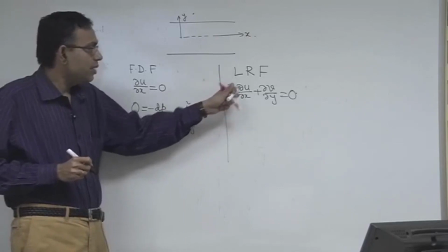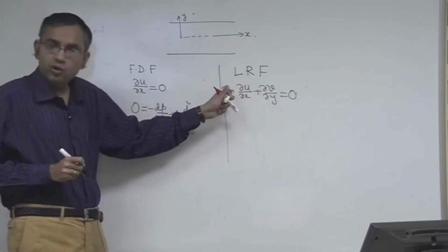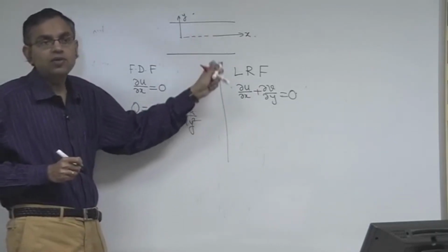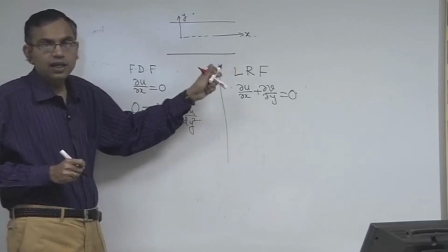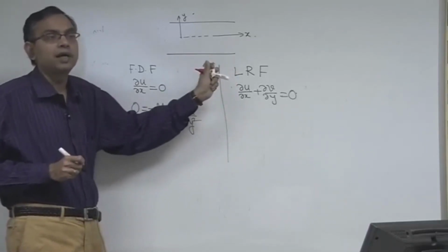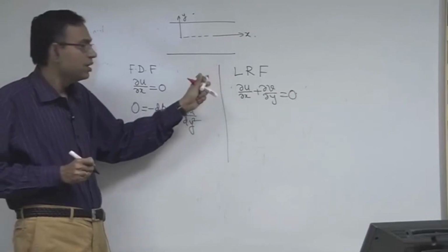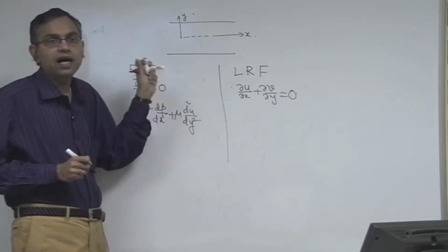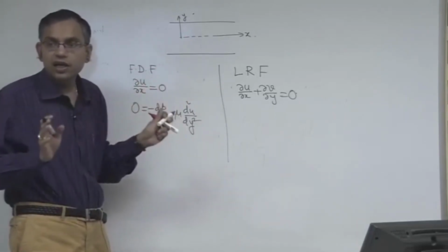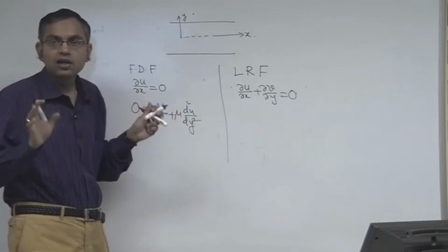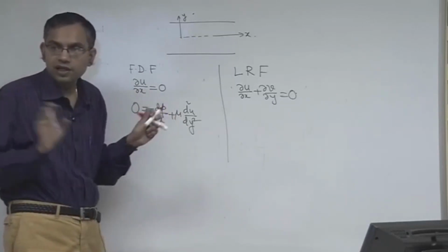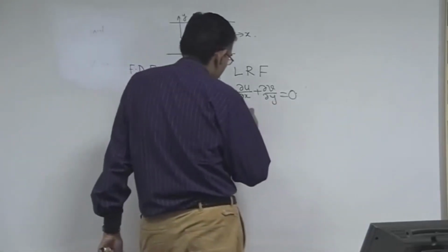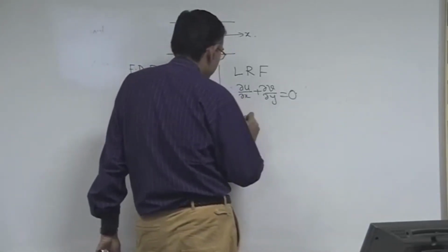So, V may be small as compared to u if the length scale along y is much smaller than the length scale along x, but if the length scales are comparable u and v may be comparable. On the other hand, when you have no holes on the wall of the channel, then for fully developed flow V is identically equal to 0, no question of any approximation, nothing is required. Not only that, the x momentum equation